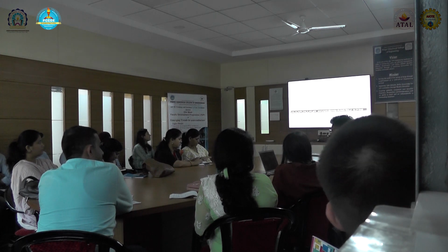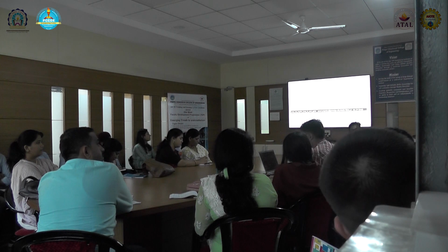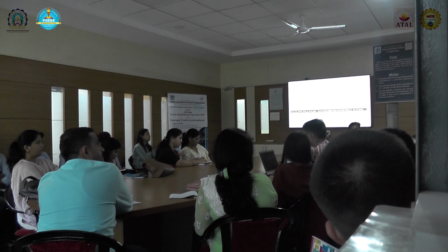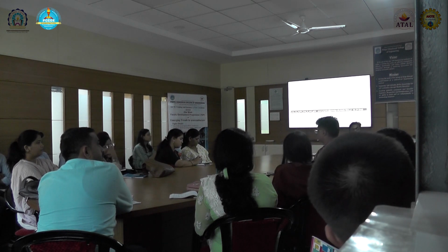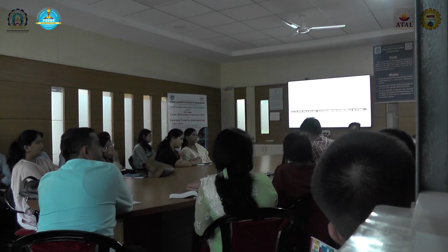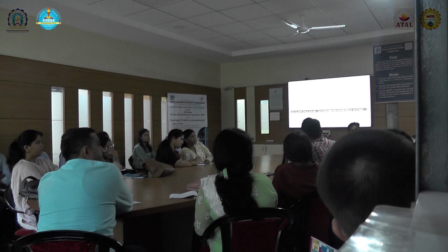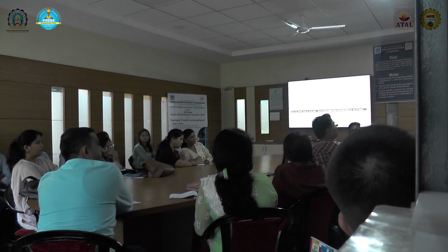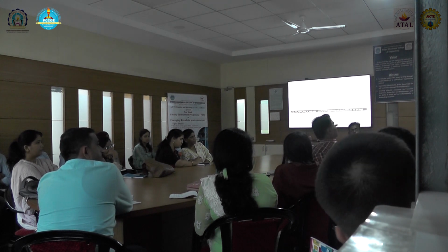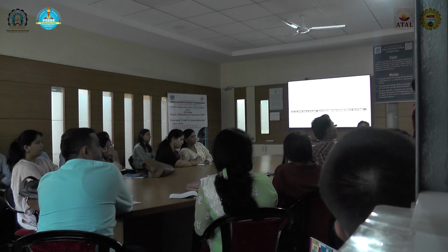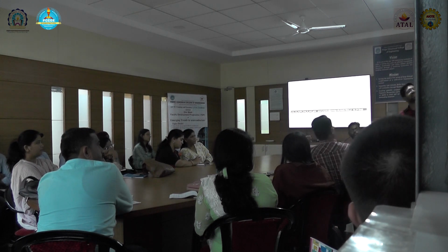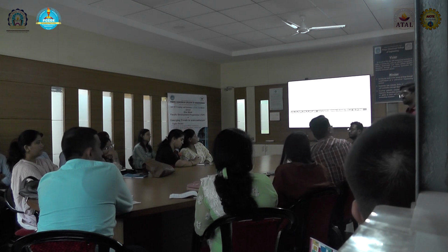It means if your something is getting triggered in this cycle, I will remember it is 1, 2, 3. So if you want to check in the next cycle, you will use this operator. It will get triggered here, but it will check in cycle number 3. But if you use this operator, which is a single line, it will check in the same cycle at this point. So this operator means check in the same cycle, and if you have equal to, it means check in the next cycle.